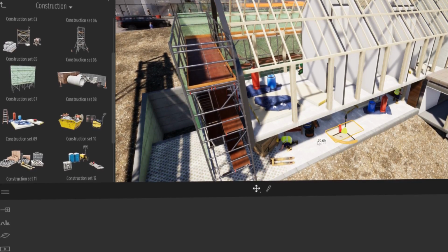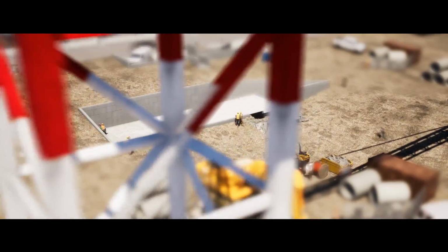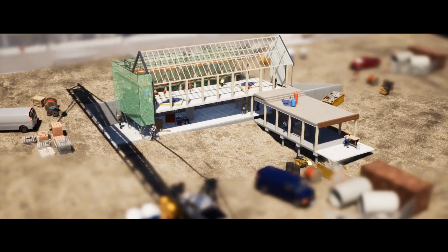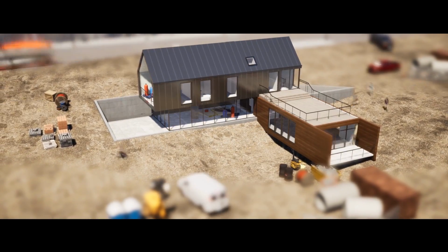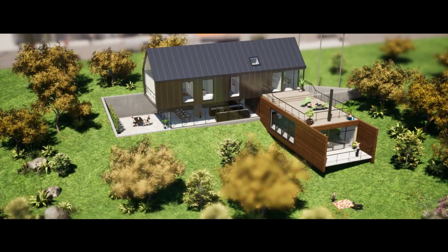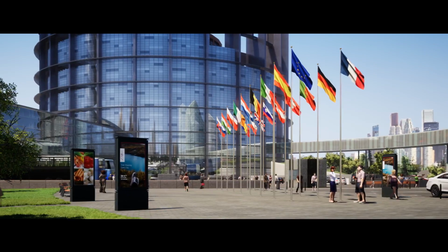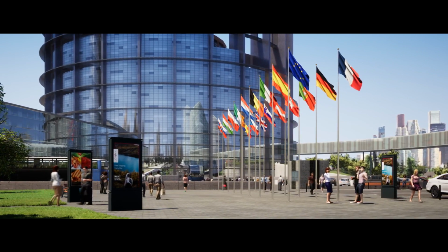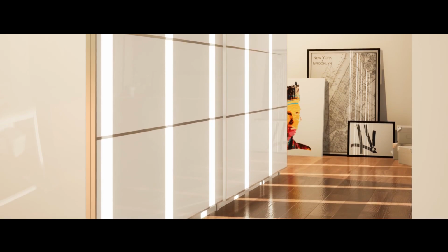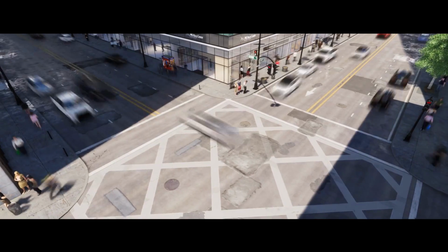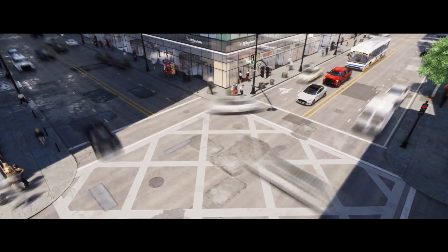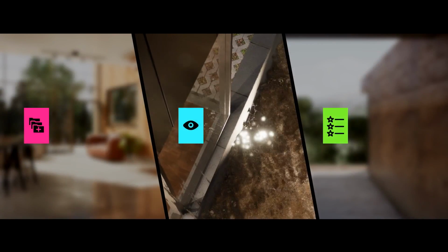For example, Twinmotion can handle millions of polygons, but not thousands of objects. So the first thing, when you know that you want to create a VR experience at the end, you really need to optimize your project, you optimize your file. For example, you don't need to have all the screws, all the really small pieces of items that you don't even see in the viewport.